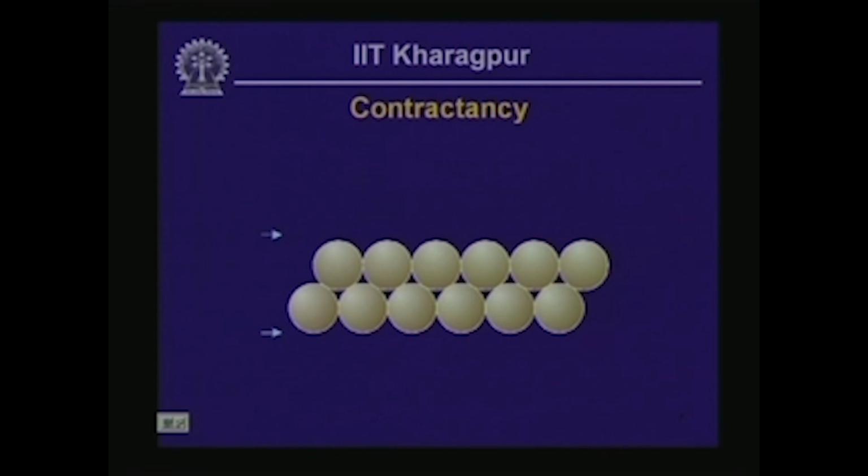So, if you have got a specimen which was originally loose, then if we apply shear stress, we are going to reduce the void ratio, and we are going to end up with a state of packing which is a much denser assembly of individual soil or rock fragments.